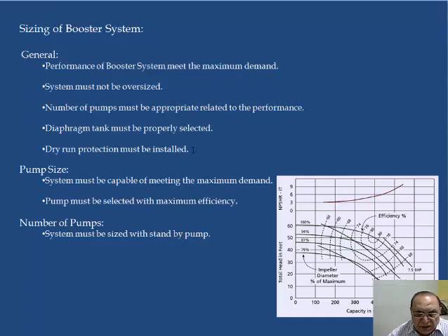And dry run protection is required when the water has been exhausted in the tanks; the pump should not run. The sizing of the pump has to be as per the maximum demand, and pumps must be selected with the maximum efficiency.